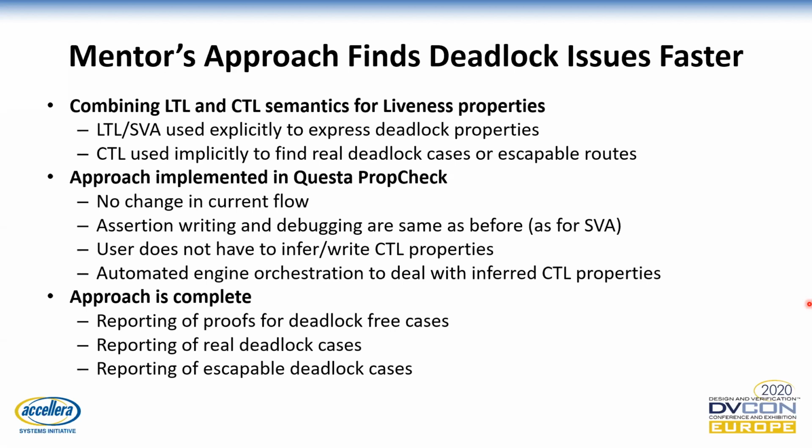LTL is used as before, explicitly for writing properties. CTL is used implicitly to analyze deadlocks. This approach was officially added to Questa PropCheck two years ago. I have to say that enabling this CTL checking in Questa PropCheck has no impact on the flow. The way that you write and debug assertions is the same. You are also not required to make any engine orchestration for the CTL engine. This will be done by the tool itself automatically.